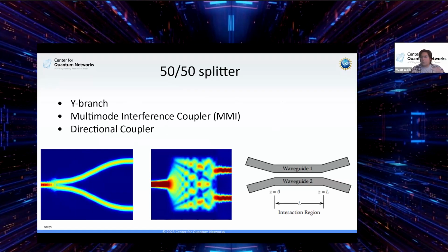So from there, after you etch, you just put on your top cladding. That can be done in several different ways. You could try to put an SiO2 layer on top. You could try to spin coat on some sort of resin. That's something that I've done. But once you have that cladding on there, you have your device made. So now the next question: what devices am I going to make?